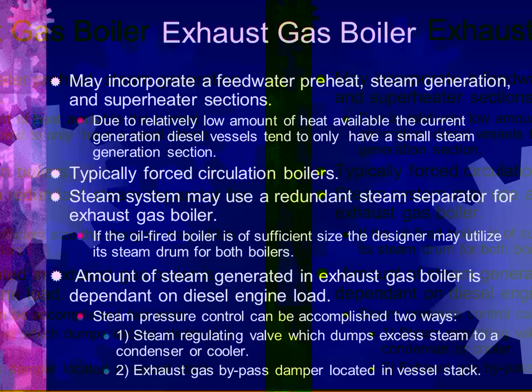And out at sea, you will be producing steam through your exhaust gas boiler, and the oil-fired will be shut down. If your oil-fired boiler is big enough, the exhaust gas boiler will use its steam drum. If not, it may have its own separate steam drum.